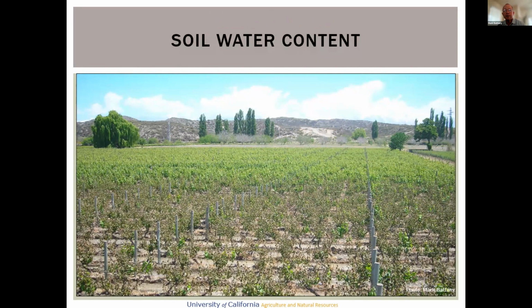And why is the difference? Well, they had run surface irrigation in two separate sets. The background had been irrigated prior to the frost, so it had a lot of moisture in the soil. The foreground, they had water scheduled to be put onto this block after the frost. So basically, you're comparing dry ground in the foreground and wet ground in the background. And it really shows very clearly that that small difference in soil moisture had a very large difference in the resulting air temperatures at the site.